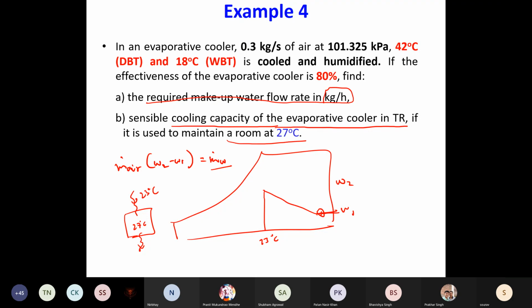So that's why when we have a desert cooler operating in a room, we always tend to keep a window or a door opposite to that desert cooler, if not completely open but partially open. Otherwise, your room will become very humid after some time.